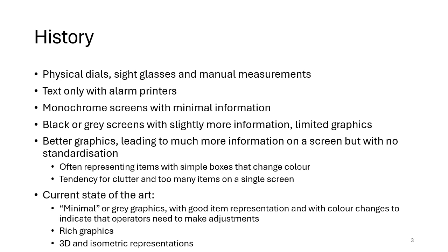I've been on one site where red was stopped, which is the safe state, and on the same site on a different graphic, red is an alarm state, which is a dangerous state. So in the same plant, in systems which are very near to each other, the same color could indicate different things. So lots of opportunities there for misinterpretation and confusion if you don't have good standards for the way you develop it.